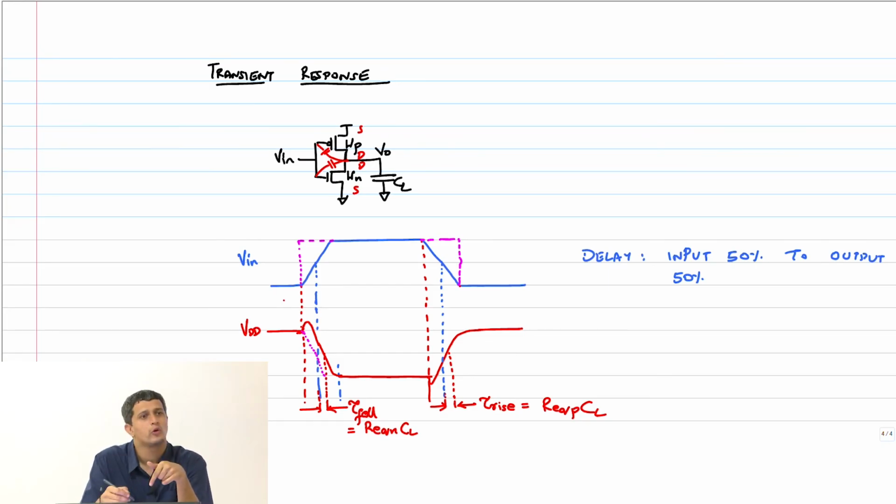That's why it's not following exactly. It's not, for example, this node is just not going up like this, right? The input is actually going all the way to VDD. That's not happening. It's just that momentary thing, it will go, and then of course the NMOS transistor turns on, and so therefore it will fall. So there are multiple effects happening there, right? One is the capacitor which is causing this coupling. The other is the NMOS transistor is now turning on. So now that will pull that node voltage down, right?